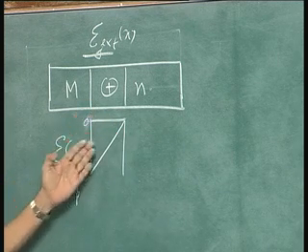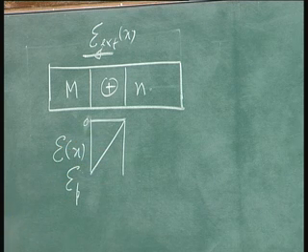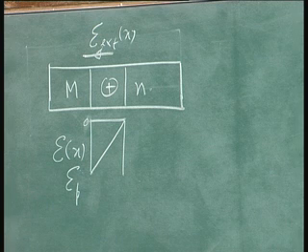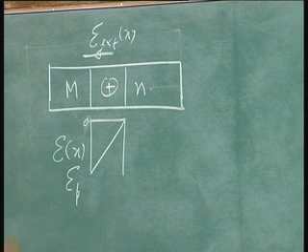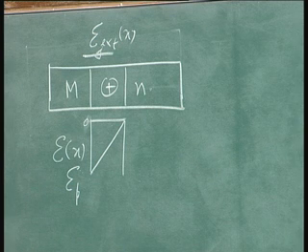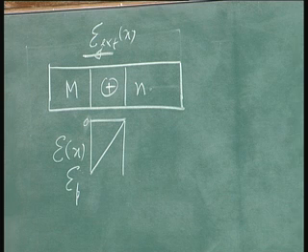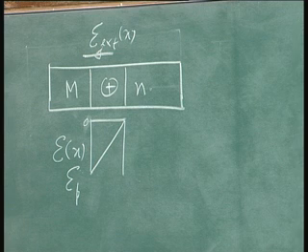Now, you integrate that. This particular field, what you have plotted there, is linear. If I want to find out what the potential is here, that potential in thermal equilibrium is the built-in potential. When I apply forward voltage, it is V_bi minus V. When I apply reverse voltage, that is V_bi plus V_R. So, that is all what this is. We have been discussing this so often; I am reiterating what we have been telling.